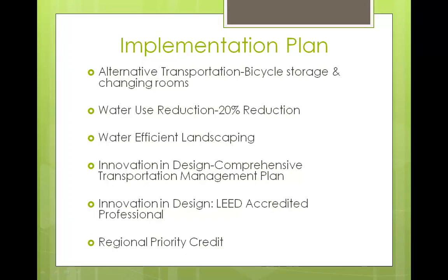To increase the LEED certification level, we are going to implement our implementation plan that will make the building more energy efficient. The first thing that we would address would be Alternative Transportation, Bicycle Storage and Changing Rooms, credit 4.2. A covered secure bicycle storage area would be added to the specifications, and it would be located on the southeast corner. Also, 1 shower will be required for the full-time staff that will be commuting on bicycles.